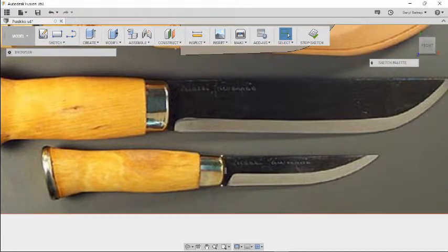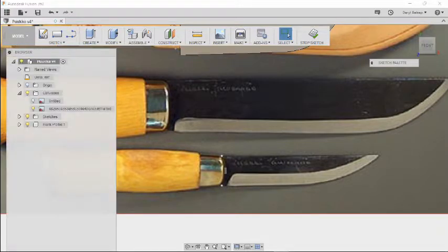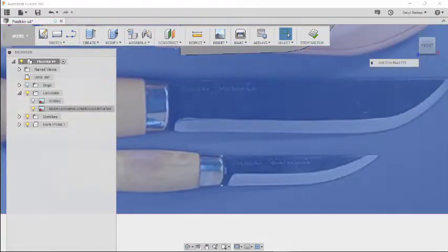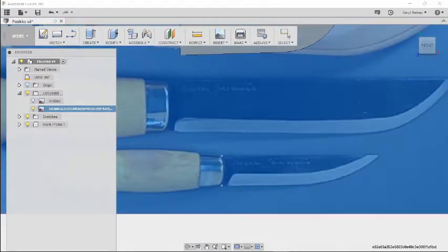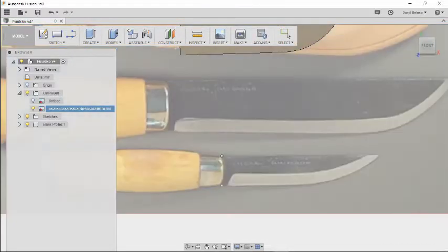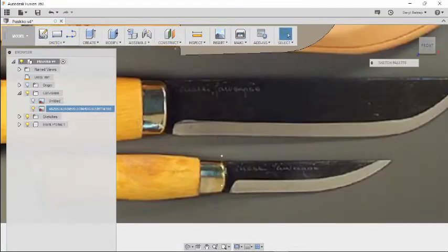Now we're going to calibrate our sketch, or calibrate our canvas. We'll go to calibrate. I'm going to click on this point right here, and then click down here again. I'm going to call that 20, so that rescales the drawing. Go ahead and delete that line. It's not necessary for that there.